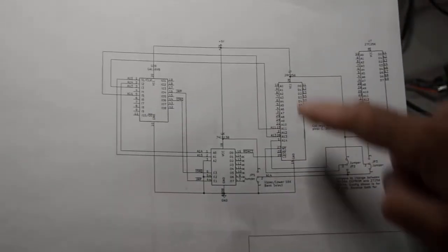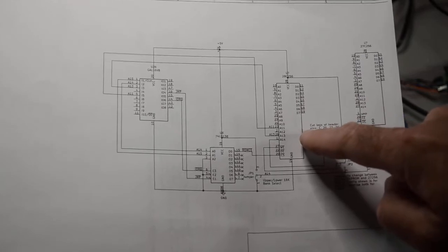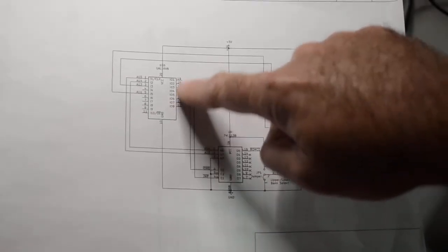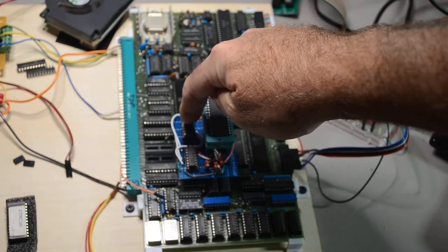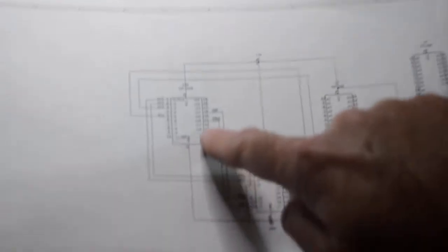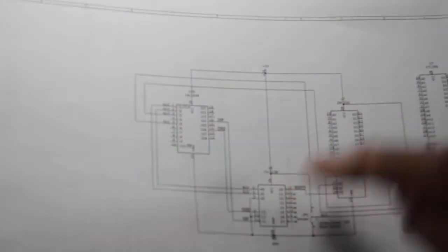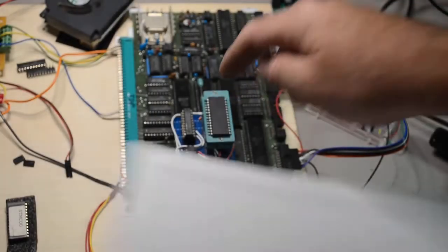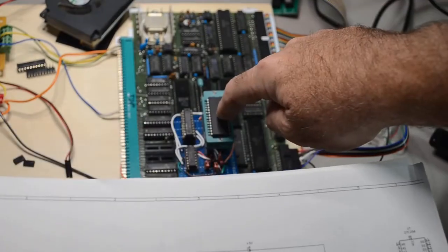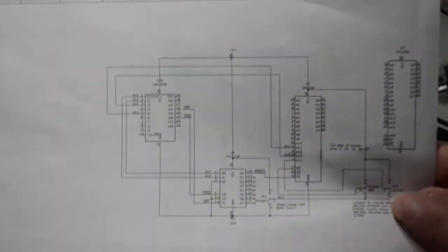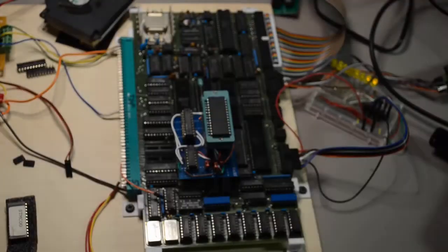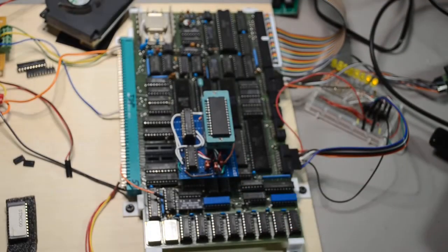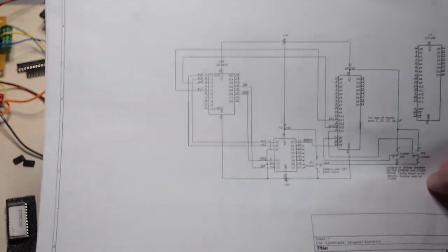Basically what I do is I take out the existing EEPROM and I take out this PAL chip over here. I build a daughter board that plugs into their sockets. I put the PAL chip back in. I steal some signals from the PAL chip, okay? And of course I've got all of the signals for the EEPROM socket up here. I add an extra address decoding chip down here, 74LS138. That's that one there, and some jumpers, and hey, I'm good to go, right?